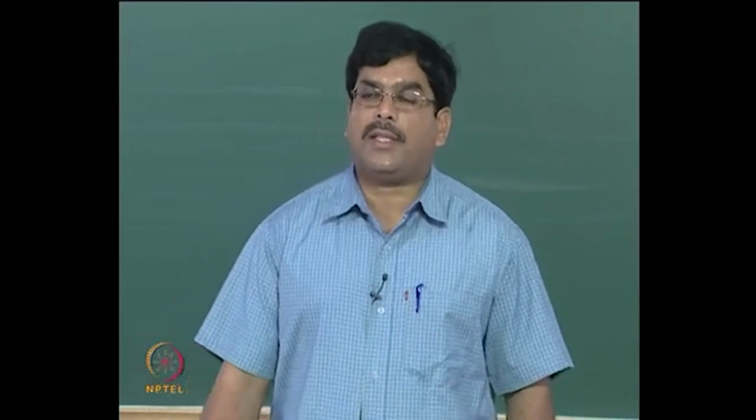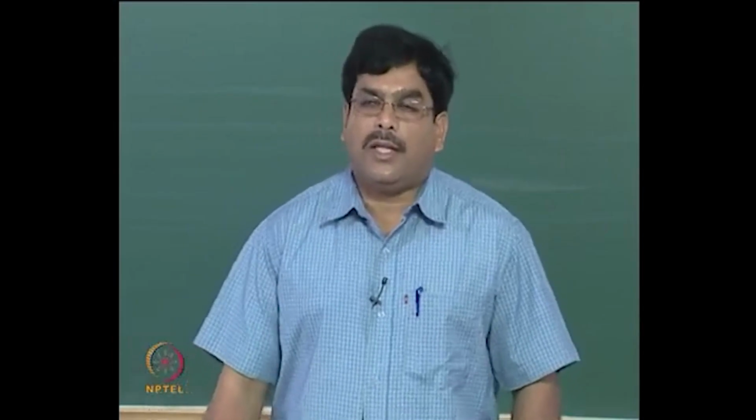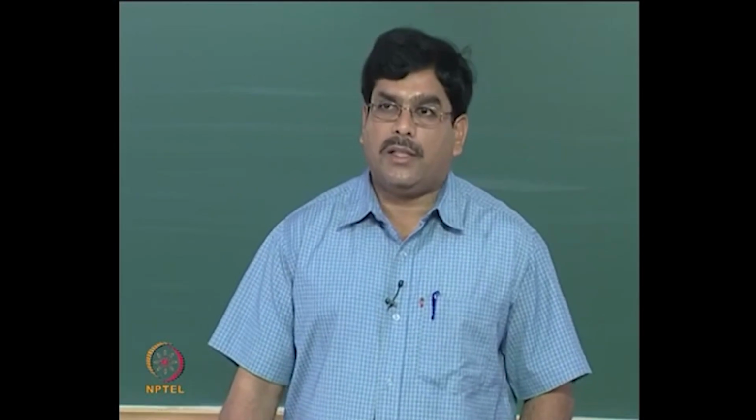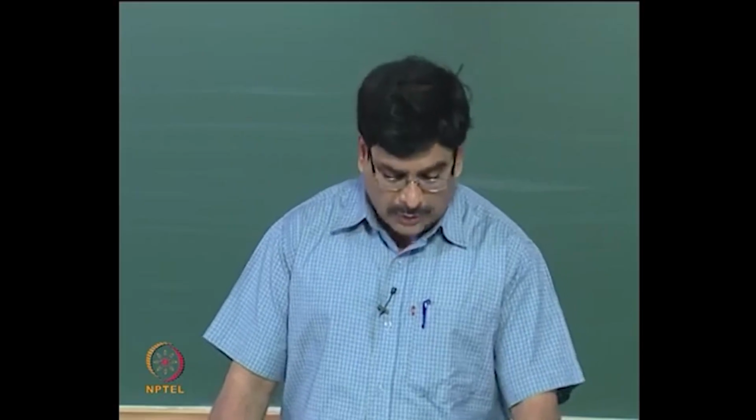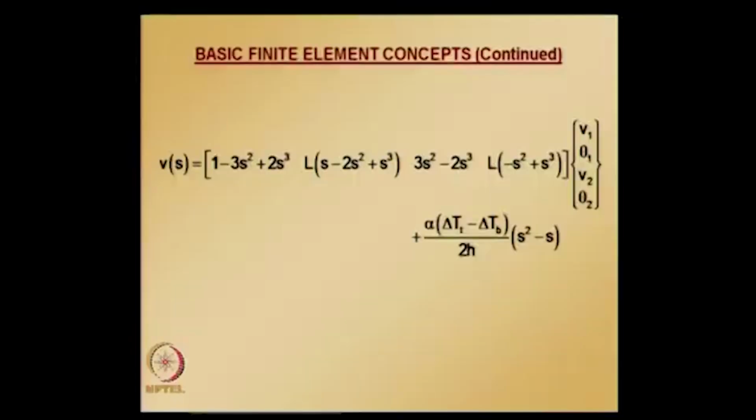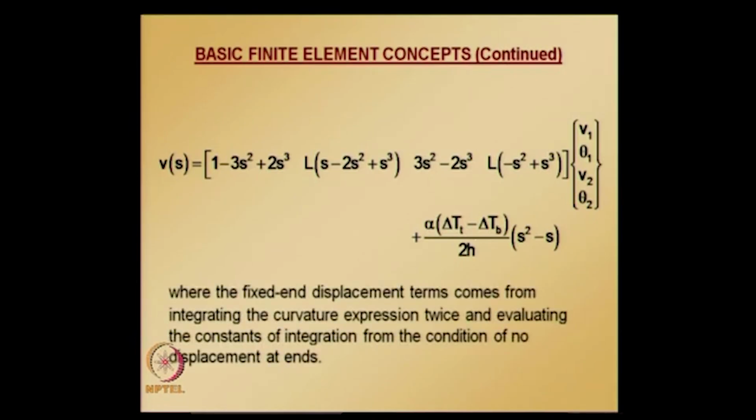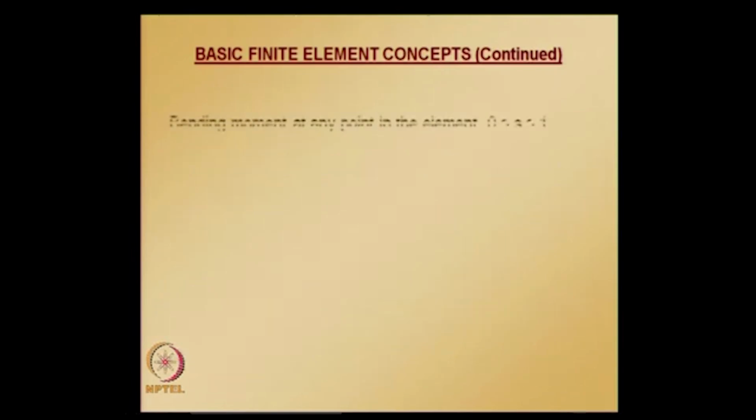So, adding this fixed end solution to the finite element solution, we get the accurate solution, where the fixed end displacement terms come from integrating the curvature expression twice, evaluating constants of integration from the condition of no displacement at the ends.